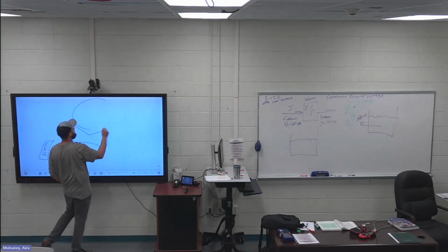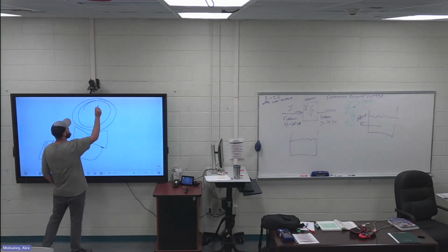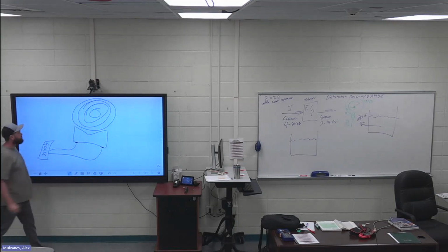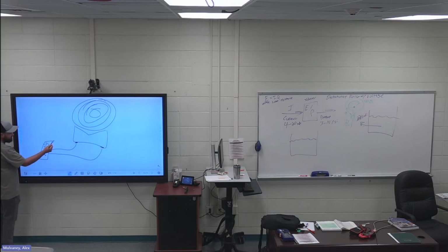Where I worked in the steel mill, we had big coils of steel, right? So how we calibrated this scale was we took all the weight off of it. Then there were buttons on the back of this, a 0 and a span. Took all the weight off, push the 0 button. That's just like your little cooking scales.